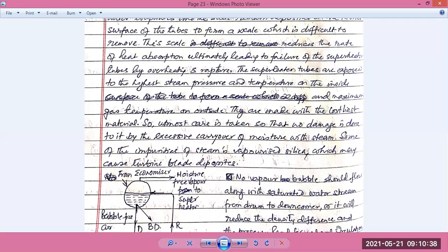So what the steam drum receives from the riser is, first of all, the saturated water and steam, as well as slags, which contain different types of salts and certain foams, and which are also detrimental for the steel tubes, because they are created due to the reaction of the salts with high heat, and all are absorbed inside the drum itself.